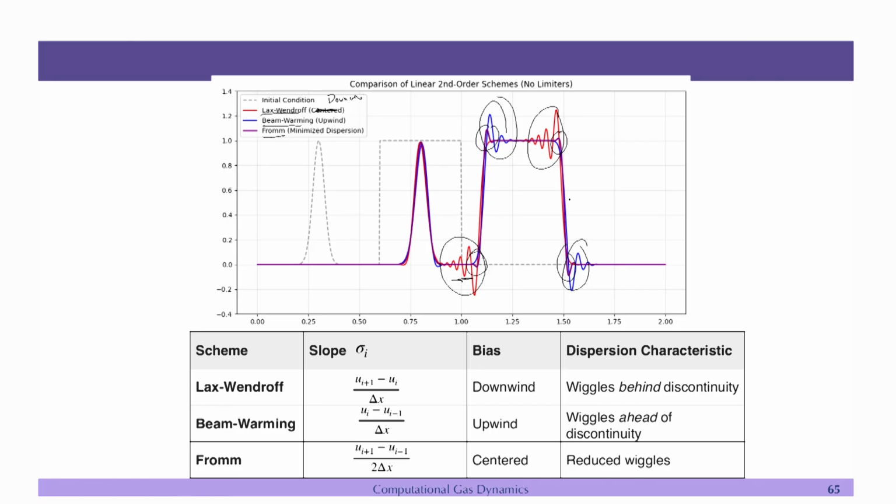And this is the square wave, this is the propagation of this square wave. We are also propagating a simple Gaussian wave, and you can see that all these three schemes preserve the magnitude a lot. If you use the upwind scheme, it will become something like this, the magnitude will go down, but because these are second order, they will behave very well if the solution is smooth, right. But as soon as you have some discontinuities like this, you will start seeing this behavior where you have a lot of wiggles. So, these are some of the properties that we have discussed here already.